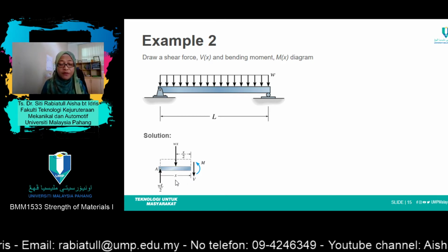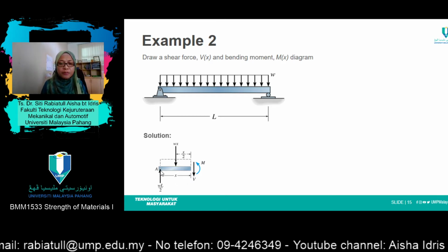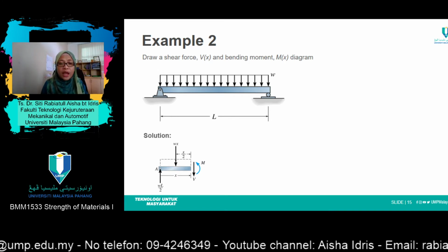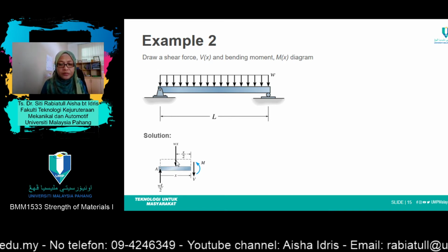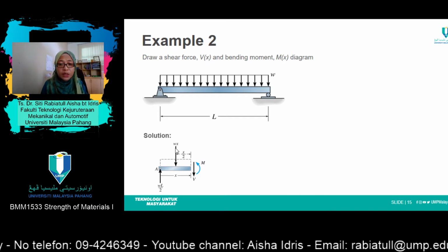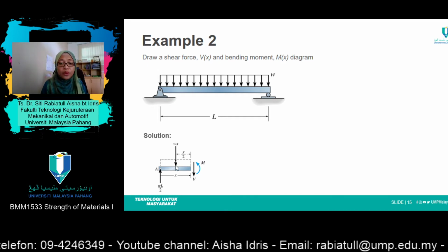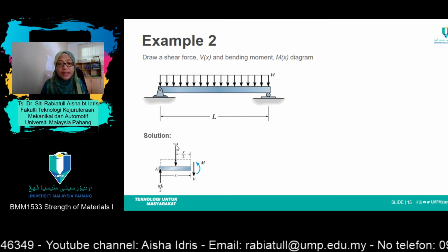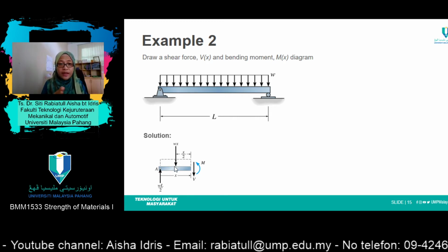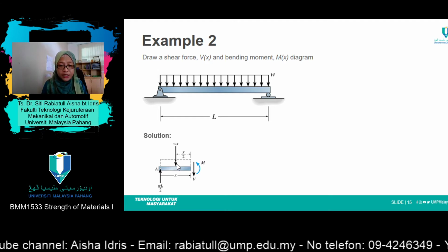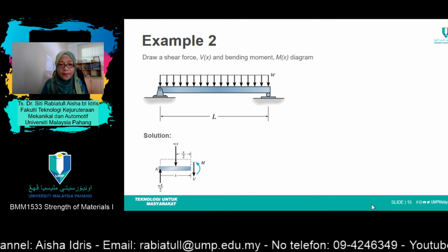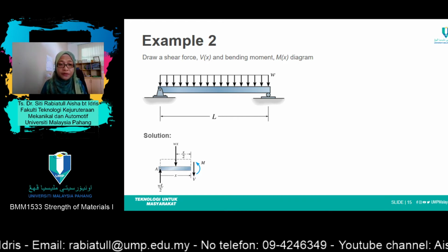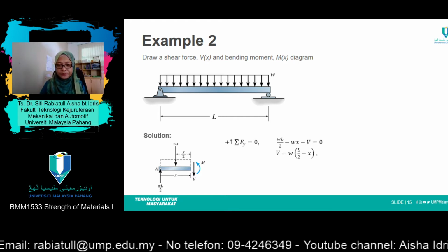For example, if you cut from point A until X, the resultant force is W times X, and it acts in the middle of X, which means X over 2. From there, you need to find the value for shear force and also moment.